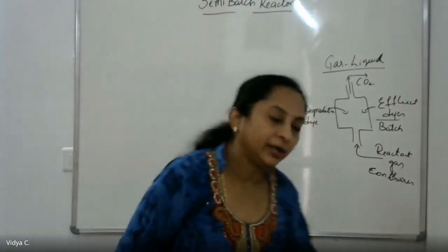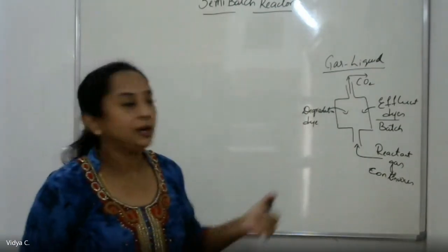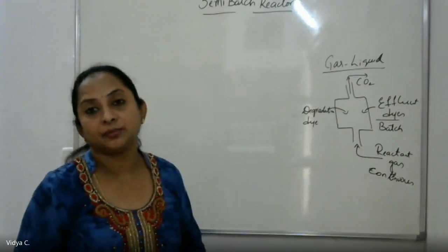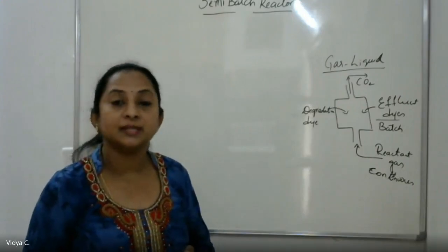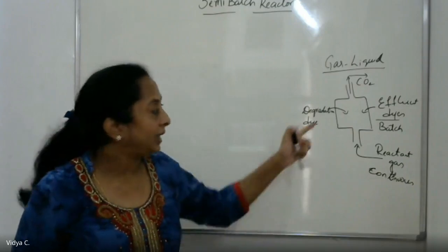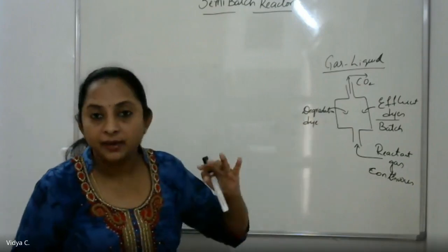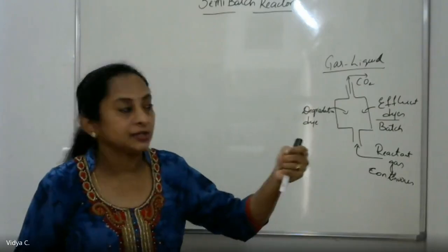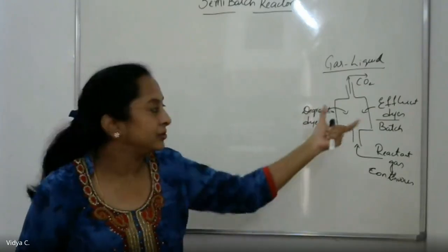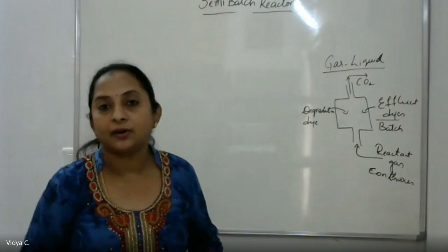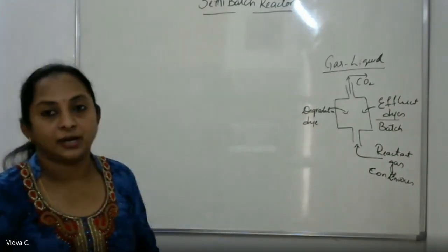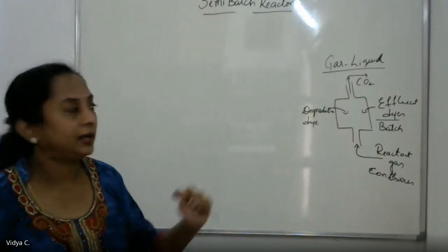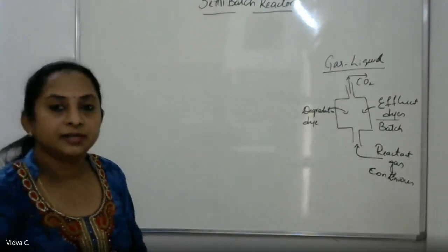And another important thing is that good temperature control can be obtained in a semi-batch reactor. If the reactions are highly exothermic, then such reactions can be carried out in a semi-batch reactor by altering the flow rate or the concentrations, and can be safely and comfortably carried out. So selectivity and temperature control are very important advantages of a semi-batch reactor.